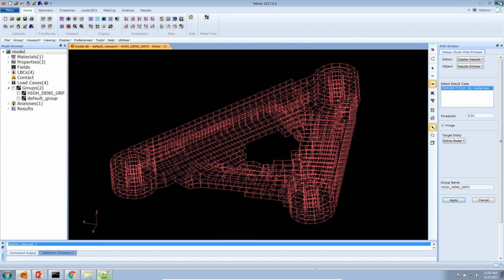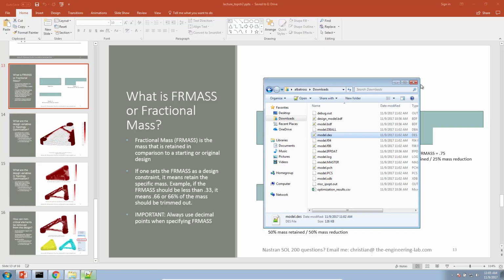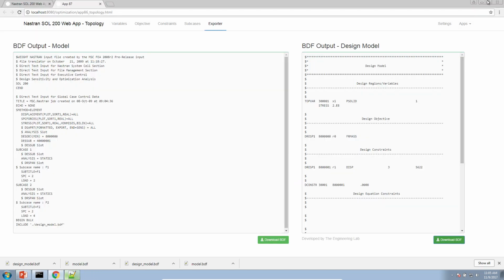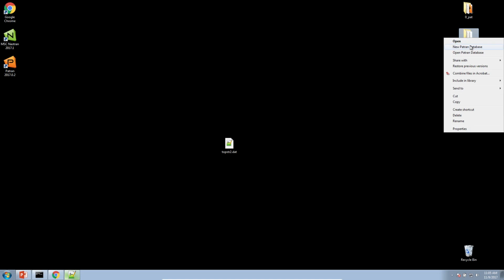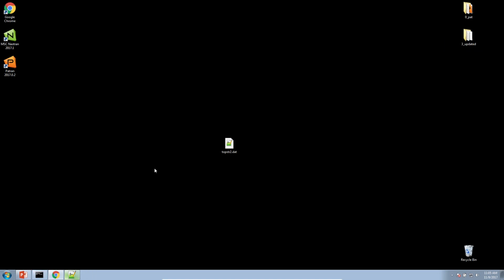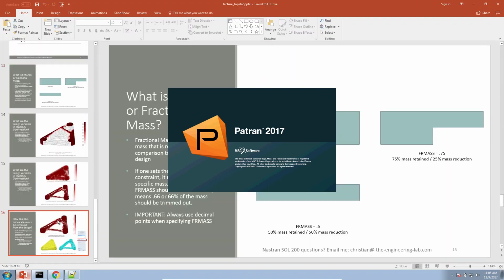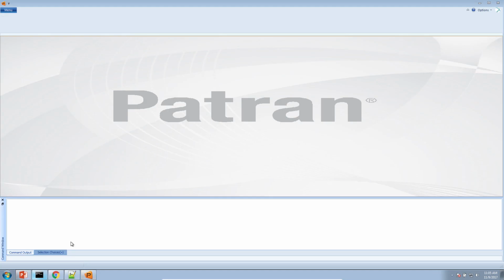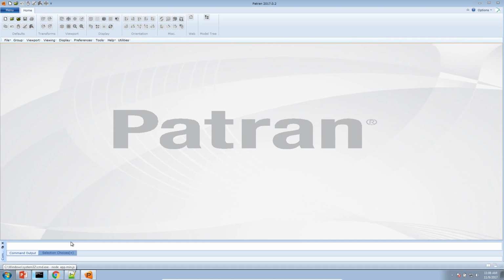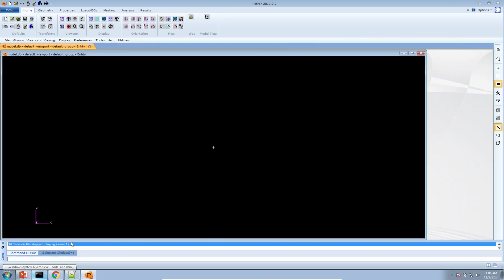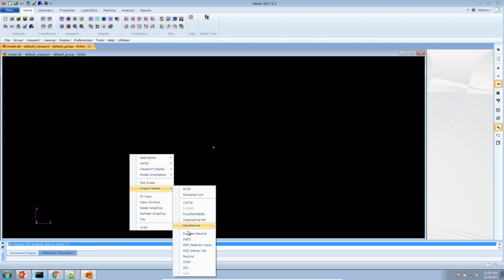Anything close to 1 means that it's very critical to the design. Now, I've already taken time to smooth out the part. So let's jump to that and review what the stress state of that new part is. I'm doing this because you always want to make sure that the optimization has honored your design constraints. So that's what I'm confirming right now.